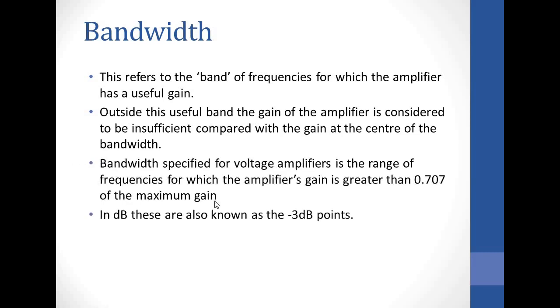So, just like in filters, we consider the -3 dB points as the cutoff frequencies. So, any frequencies with a gain less than -3 dB is actually considered outside the passband, but anything above -3 dB is considered the passband frequencies, or the frequencies we want to amplify.